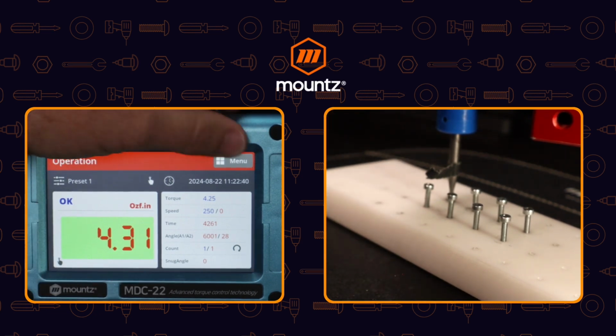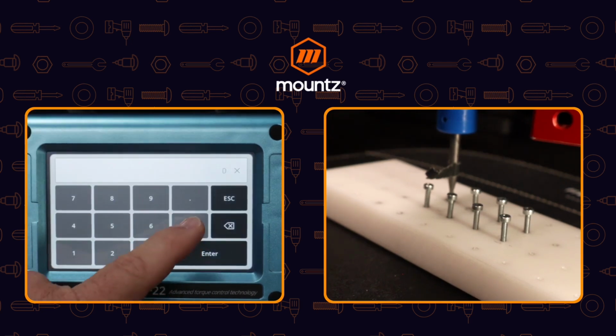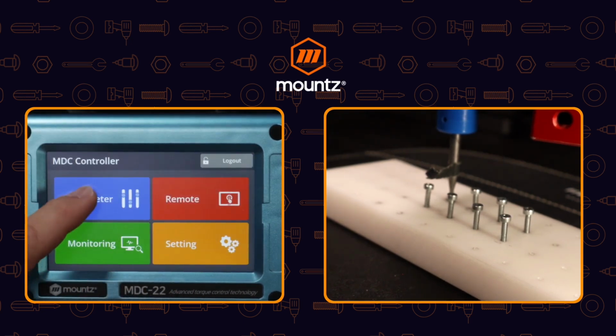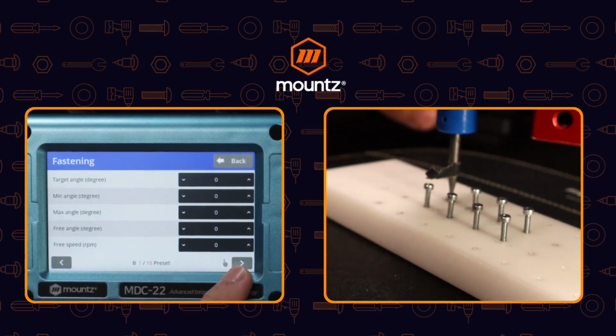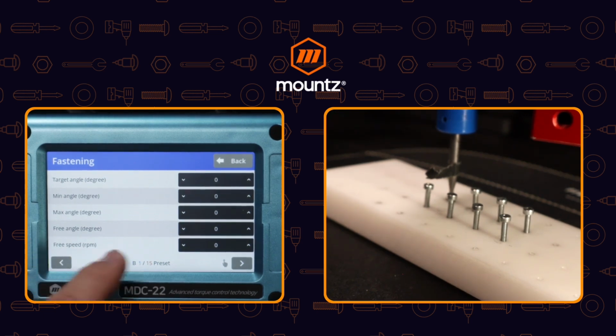We can use a scenario where we can run the fastener down during the thread engagement portion at a much higher RPM, and then allow the tool to downshift back to the seating RPM of 250 RPM. So if we come here to our free angle and free speed, or RPM, that's what we can do.